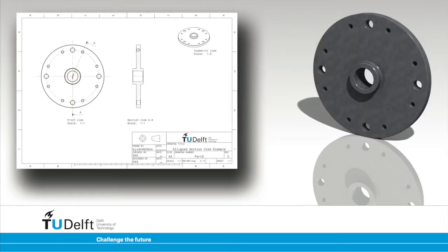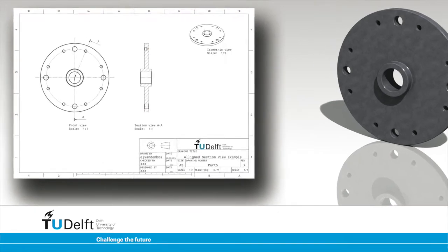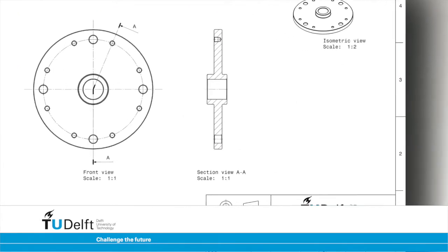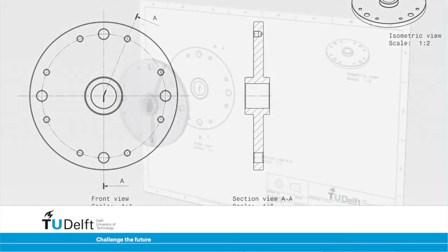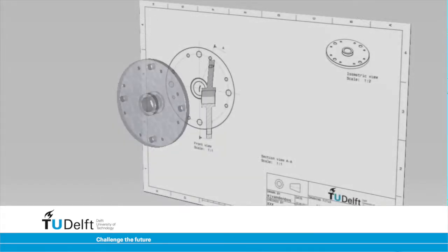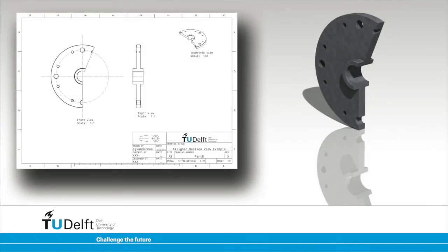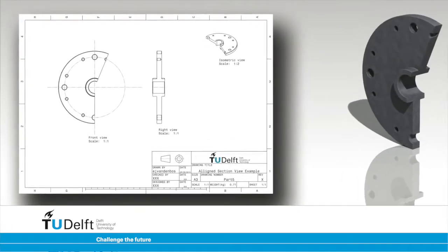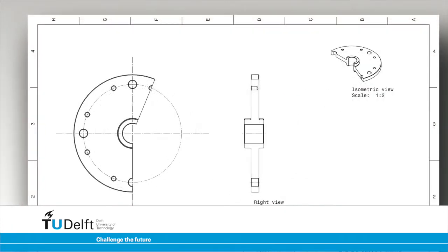In this way, the section view shows information about two different holes in a single projection view, without the holes being actually aligned. The section view is not foreshortened, but shows the geometry as if the cutting plane was vertical. This would be different in the case where the object was cut off in reality. The projection of a real cut, which, as a result, will have a face not perpendicular to the projection direction, is foreshortened.